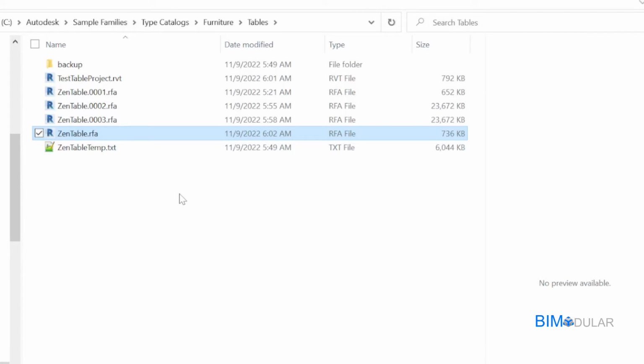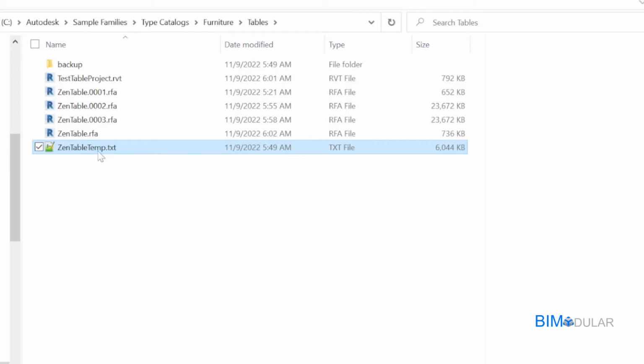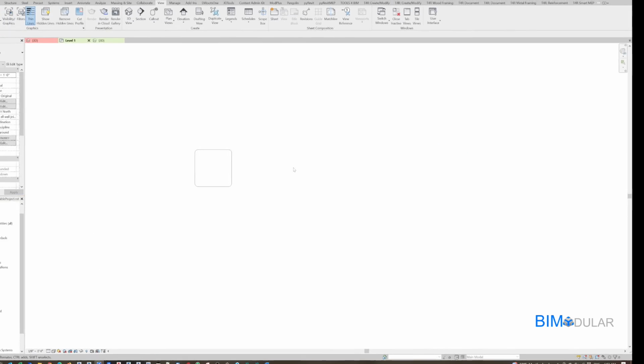So what's important is that whenever you're saving a Revit family, make sure that large type catalogs have a temporary name in place before you save, and then come back afterwards and just give your type catalog back to match. Now you've got a small Revit family, and you also have your full catalog you need of all your parts. Now let's go ahead and load in and see what happens with a Revit project when you pick a large type catalog, in regard to load time and what happens with the file size.